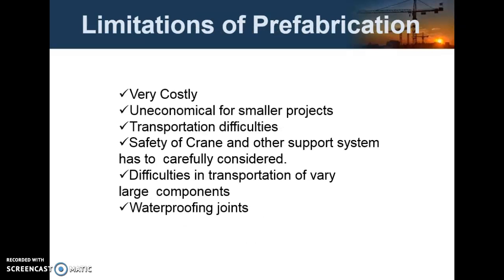Limitation of prefabrication. It's very costly, uneconomical for smaller projects, transportation difficulties, safety of crane and other support systems, difficulties in transportation of very large components, waterproofing joints.